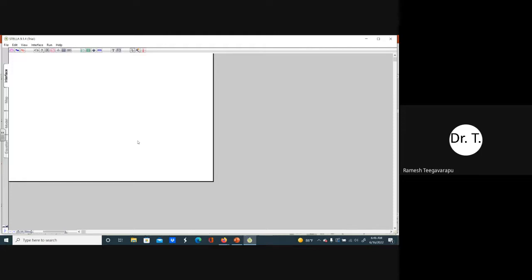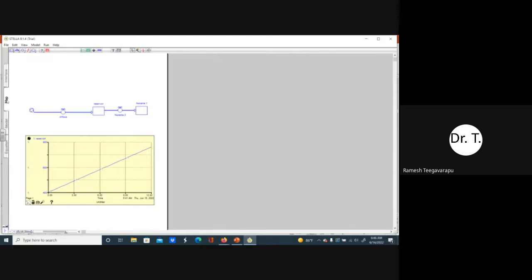I build a model for infiltration and I change a factor. Or, for example, I want to see the flood hydrographs based on some variant of a factor. I can do that by introducing an interface there with a slider or some kind of way for users to provide inputs. We can do that. And when you do the run, you see the sensitivity specifications. That means you are doing sensitivity analysis, and you're also doing it by sectors. That means you can make the whole thing as one sector, and you can run only one sector.